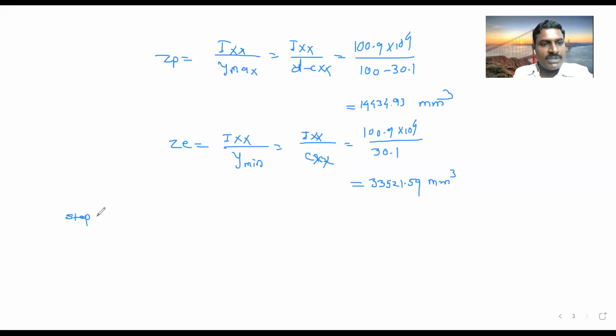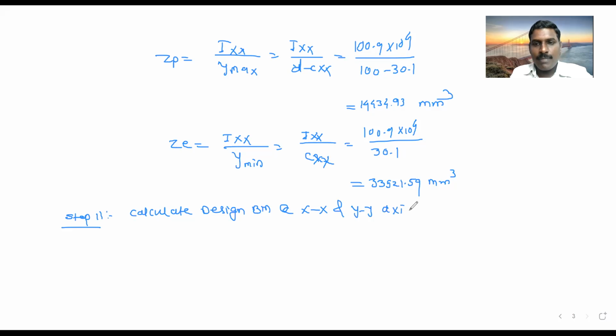Okay. So then go to the next step, step number 11. So what we have to calculate in step number 11? So we have to calculate the design bending moment along the x-axis and y-y axis. Okay, design bending moment for angle section.